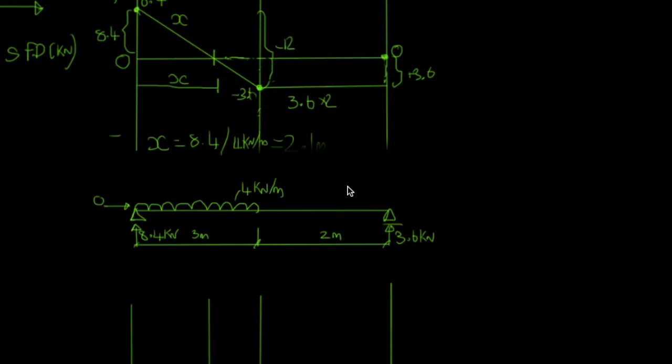Okay, so now on to our bending moment diagram. This can now be achieved because we've first calculated the reactions in our beam, and we found the shear forces, and now we can calculate the bending moment diagram, the final step in the procedure. So as before, we're going to work from left to right, and this is going to be our bending moment diagram, and everything's in kilonewton meters.